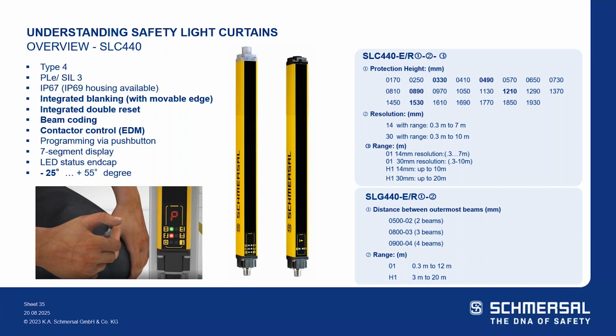So your beam coding allows that light curtain to be mounted in close proximity without crosstalk, and you can program that in. And onboard contactor control, so your onboard feedback monitoring loop, your downstream monitored motor control contactors and relays.